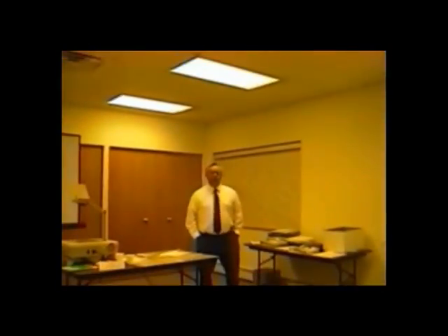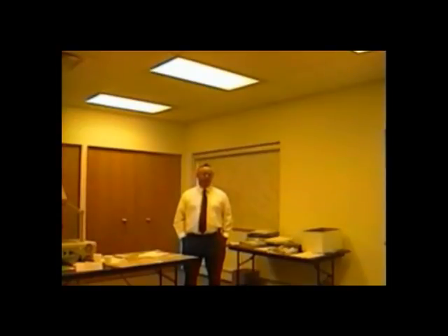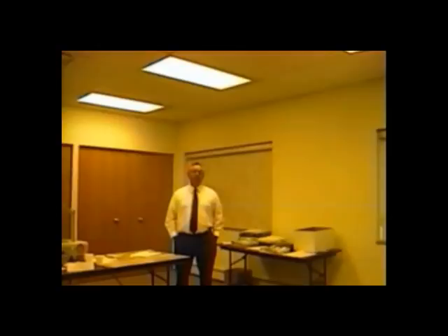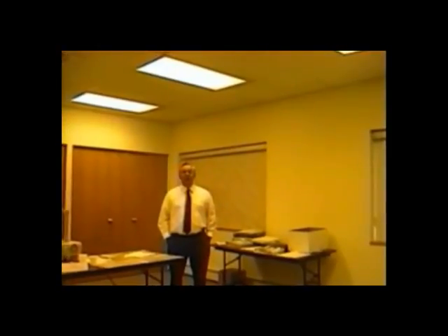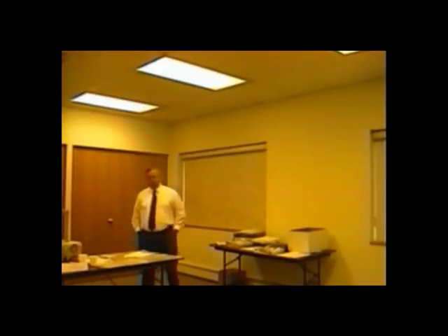Or how about if we charge everything until we get 20 degrees of superheat? Well, that's not true either, ladies and gentlemen, because our superheat varies all over the board, and I'm going to show you that. So keep in mind, I'm going through some methods that didn't work here. We're doing this very quickly, so I'm going to show you some methods that absolutely work perfect. They are so easy today. We're going to make your life so easy with this, and you'll be able to diagnose problems as well.